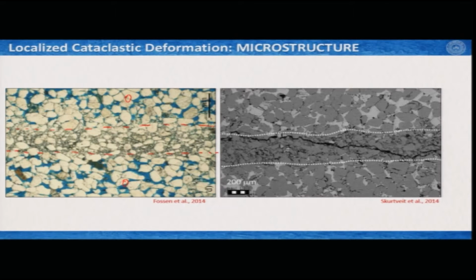If we measure statistically, the grain sizes here are a little reduced from what we see outside, and at the same time the porosity has also reduced, and the number of small or finer grains along this narrow zone is quite significant. As I said, this length is about 1 millimeter, so we are looking at about 1 millimeter scale. This is a very narrow or thin zone.